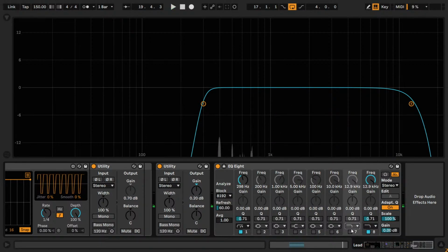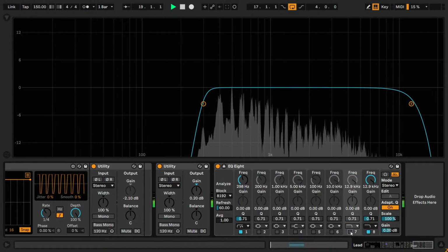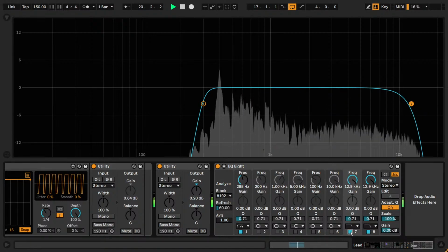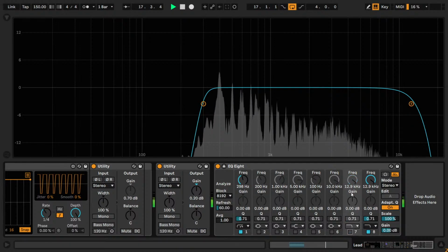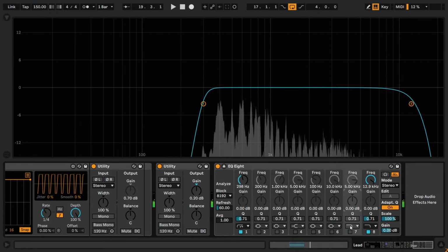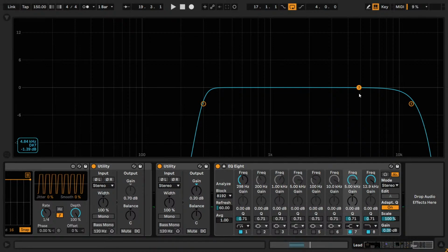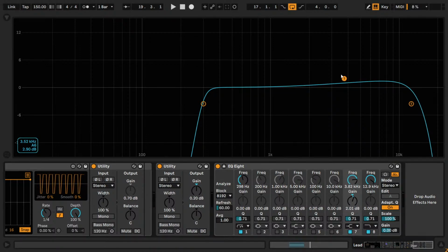We will keep a low pass filter like that. After using a low pass and high pass filter, it would be time for me to try to use low and high shelf filters to further build the frequency balance between the lows, mids, and highs before I actually use peaking filters to make more fine adjustments.